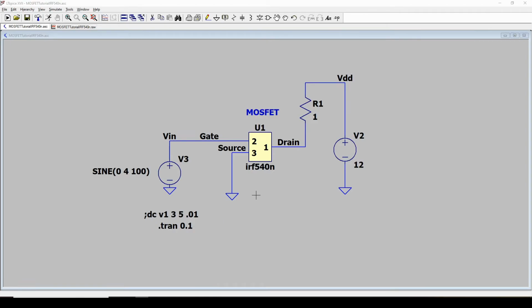Okay, so now we know that in a very simple perspective, with this particular MOSFET, when you change the input voltage to the gate from around 2 to actually more like 3.6 and above, it changes the resistance between the drain and the source. And it starts out at infinite and goes down to very low, less than 0.1, okay? So positive voltage changes the resistance.